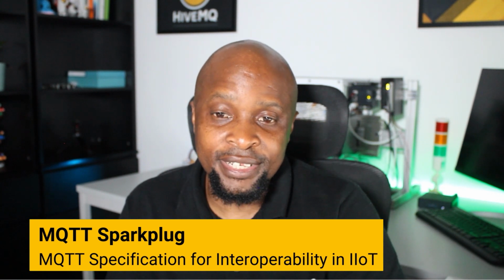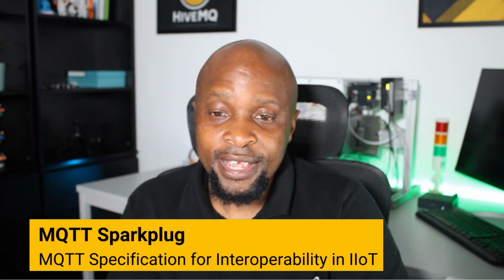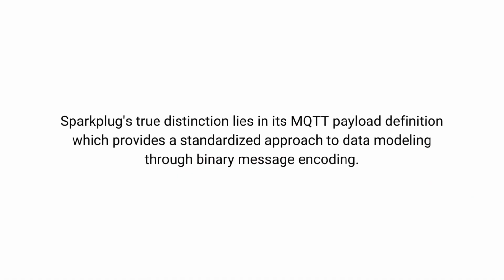Sparkplug offers a specification that enables OEM device manufacturers and application developers to build comprehensive and interoperable SCADA or IoT solutions, leveraging MQTT as the core messaging technology. Beyond establishing a structured MQTT topic namespace enriched with semantic properties to ensure interoperability in smart manufacturing, Sparkplug's true distinction lies in its MQTT payload definition, which provides a standardized approach to data modeling through binary message encoding.